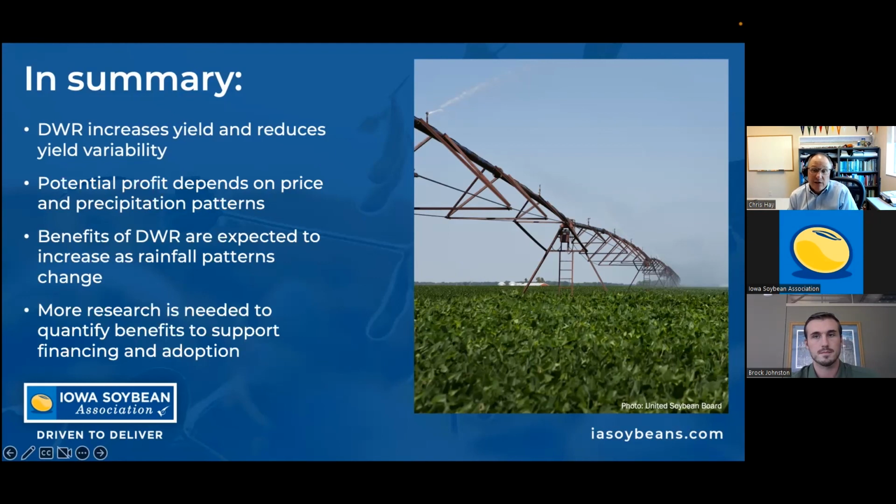The other thing is the system would have to be managed to really get those flood reduction benefits. We need that storage to be fairly empty when we're expecting those big rainfall events that are likely to lead to flooding, so that we can capture that runoff and store it, as opposed to letting it go downstream. Whereas the farmer's interest is trying to keep as much of that irrigation water as possible.